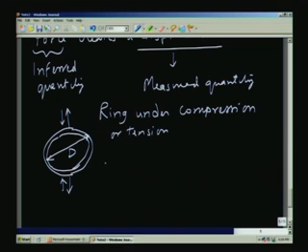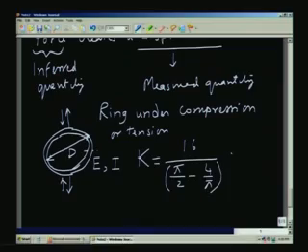and if we take d as the diameter of the ring, E the Young's modulus and I the moment of inertia of the section about its centroidal axis, you can see what is going to happen. If you apply a force like that, if you take a section here, it is undergoing bending. Therefore, the formula is similar to what we had earlier. The k value for this particular case works out to 16 divided by (pi by 2 minus 4 by pi) multiplied by EI by d cube.